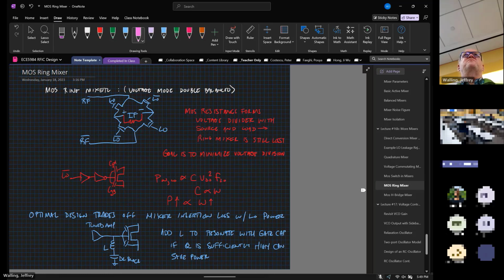They're using them to do harmonic rejection. So they're just weighting the inputs in a way that you can design such that all the signals at a particular harmonic cancel with one another, just by playing around with cosines and sines and how they multiply together. I'll share a paper that shows a more modern version of this.